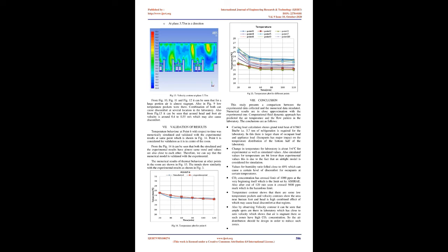The flow is assumed to be three-dimensional, unsteady, and turbulent. Convective heat transfer at the walls and windows is calculated using data of heat load calculation and outside air temperature as reference. An airtight model is assumed with no infiltration or exfiltration present in the model. Convergence criteria are set to 1 × 10^-3 for continuity and momentum equations, and for energy it is set to 1 × 10^-5. Properties of material are given in Table 2. Boundary conditions were calculated using data from heat load calculation and the ASHRAE handbook and are presented in Table 3. All the walls were considered as no slip and stationary walls. The heat flux through each wall in W/m² is given in Table 3.